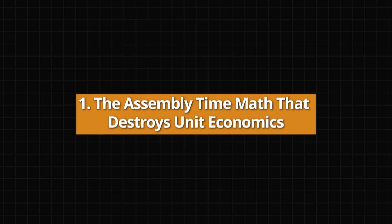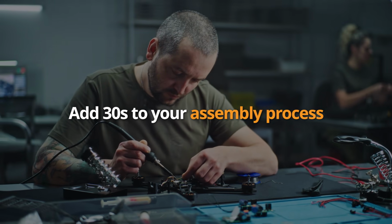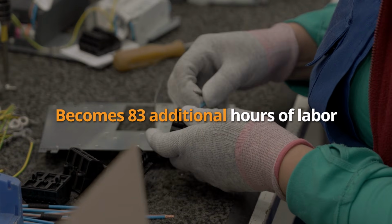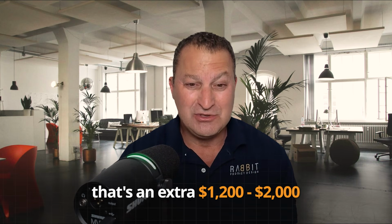Point 1. The assembly time math that destroys unit economics. Let's start with simple math. Add 30 seconds to your assembly process. That doesn't sound like much, but at 10,000 units, it becomes 83 additional hours of labor. If you're talking U.S. manufacturing, at $15 to $25 an hour, that's an extra $1,200 to $2,000 in extra costs. And that's just one small inefficiency.